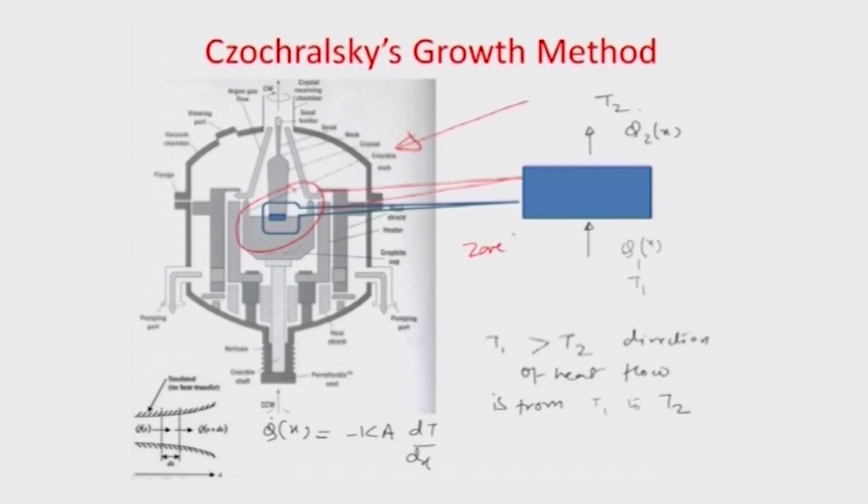Okay. It is called a zone of fusion because this is the zone where there is a presence of both the states, the liquid state which is in the crucible, and then the solid state which is a part of the seed which is getting withdrawn, and so it is a semi solid semi liquid kind of zone that we are considering.